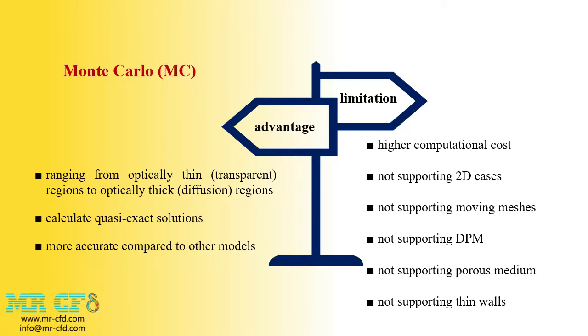The next thing is that there are things that are not actually supported by this model, things like two-dimensional models, transient solution, moving mesh, discrete phase model (DPM), Eulerian multiphase models, VOF and mixture and Eulerian, and a few others.